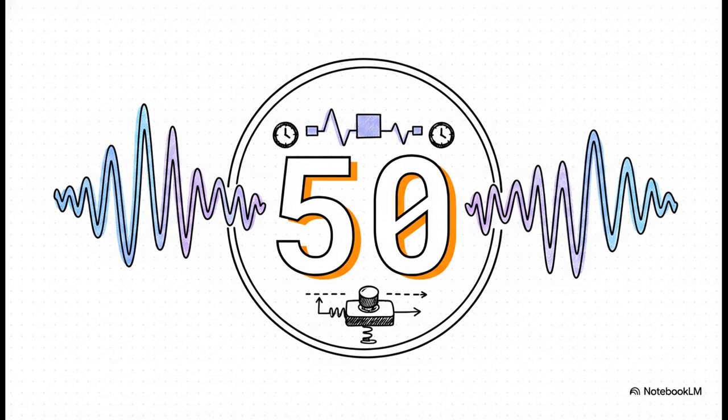And what exactly is it waiting for? 50. The code sets a strict debounce delay window of exactly 50 milliseconds. It's programmed to simply wait out the mechanical noise. The system demands a solid, uninterrupted 50 milliseconds of pure silence, a stable 0 volts, before it will actually believe that you intended to press the button.